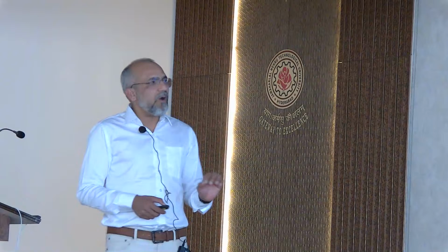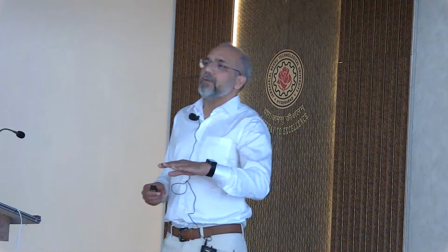And these two blocks help a lot to have a homogeneous environment in the tube. If you don't have them, then whatever precursors were going inside the tube were just taken out by the vacuum. So there was no graphene growth. And I spent a couple of months just to figure out why I was not getting graphene. So be careful when you have a recipe from the literature.